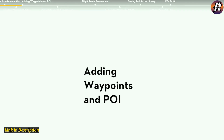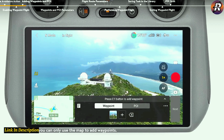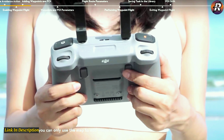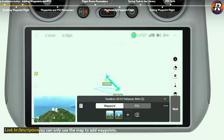Adding waypoints and POI. There are 3 ways to add waypoints. Using the operation panel, tap the plus icon on the operation panel to add a waypoint. Using the remote controller, press the FN button on the DJI RC-N2 remote controller, or the C1 button on the DJI RC2 remote controller to add a waypoint. Using the map, enter the map view and tap on the map to add a waypoint.